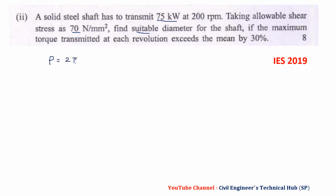P is equal to 2 pi n T upon 60, since we have RPM, and here T is T average. Then find T max. Here you will get the value of T in Newton meter. Convert it into Newton millimeter, and T max is equal to 1.3 into T average. And knowing this T, we can use T by J is equal to tau by R.